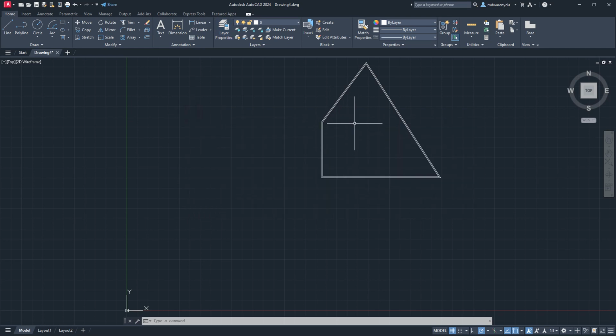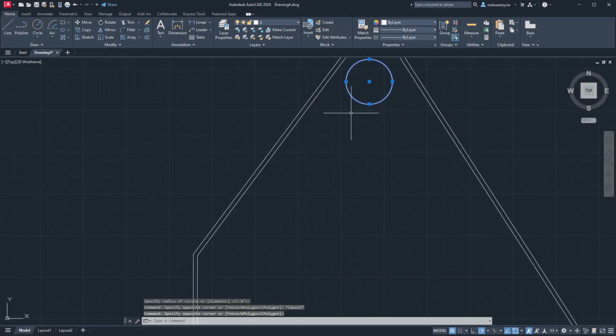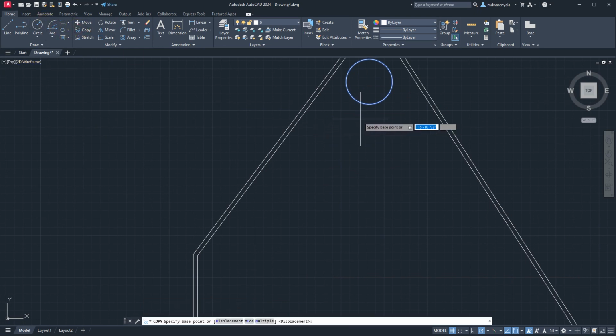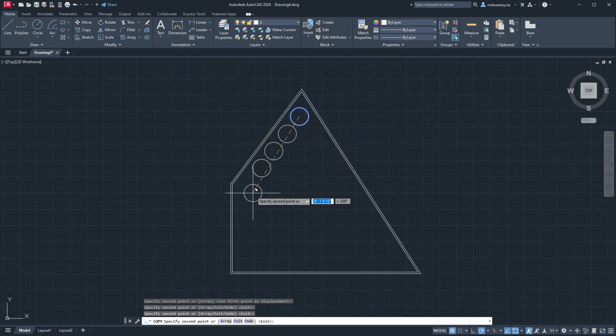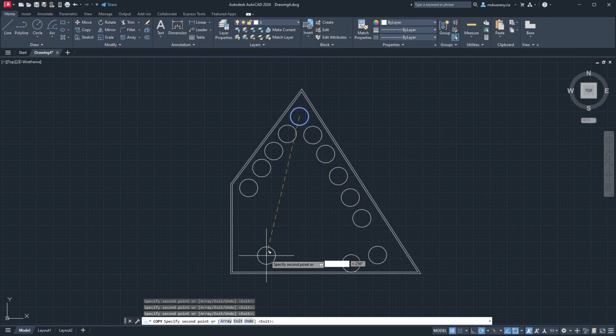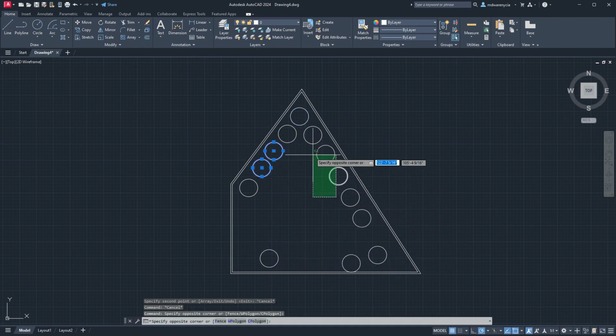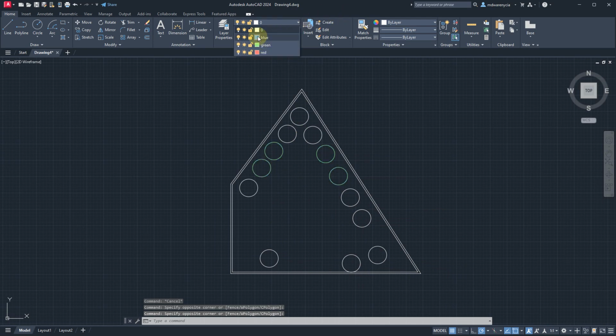And so you would organize things on different layers. Let me draw a couple things in here. Actually, let's do a move copy, multiple. Should I hit M? There we go. So if I just place a whole bunch of these around, let's just pretend that these are objects of various types. So I can assign these to the blue layer.